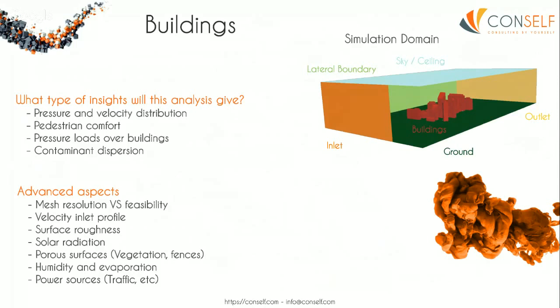But also, you cannot use cells so small to catch every single feature, because this would need too high an amount of RAM in order to run your calculation. So this is a classical trade-off you're going to face.